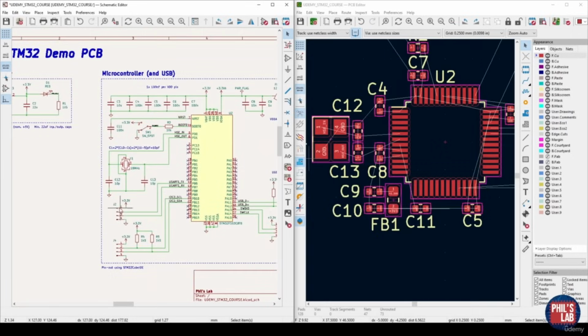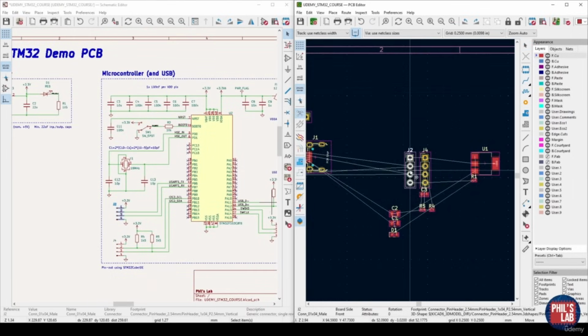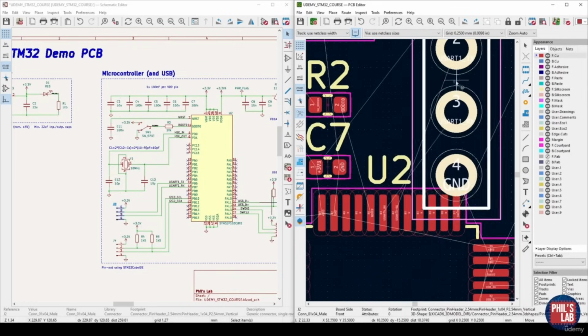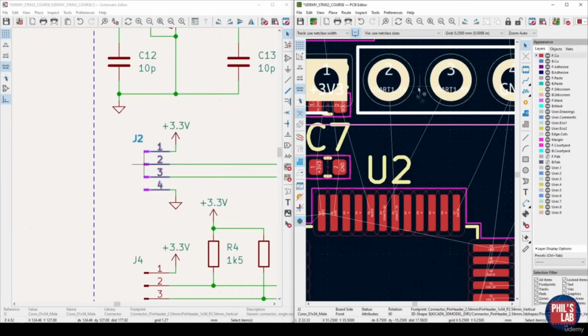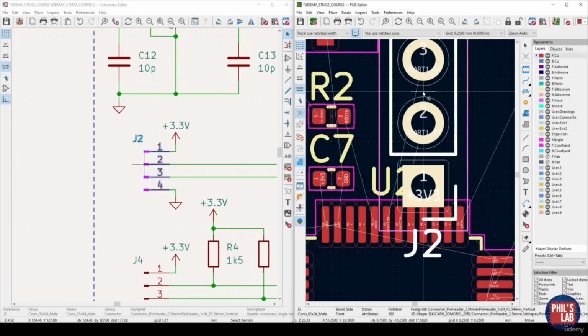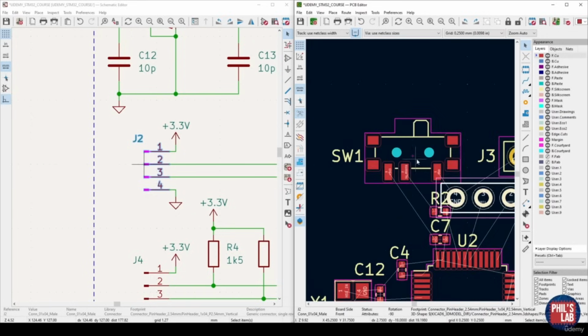Then we need our 2 connectors. So I have my UART connector over here, again using the rat's nest to guide me. That seems to be somewhere up here as well. Just checking the orientations. If I left the orientation like this, you can see these paths will cross, so I have to rotate like so. And then I can just adjust things around.